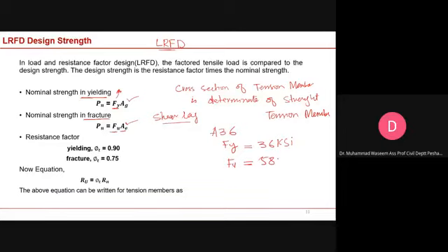58 ksi. Okay. Now, you have not asked me why it is written yielding for excessive deformation. Because if we want to prevent excessive deformation, we have to prevent yielding from occurring in our member. Why do we have excessive deformation?